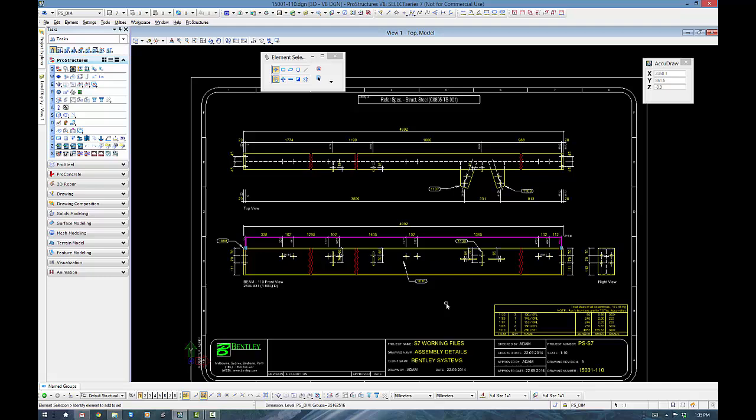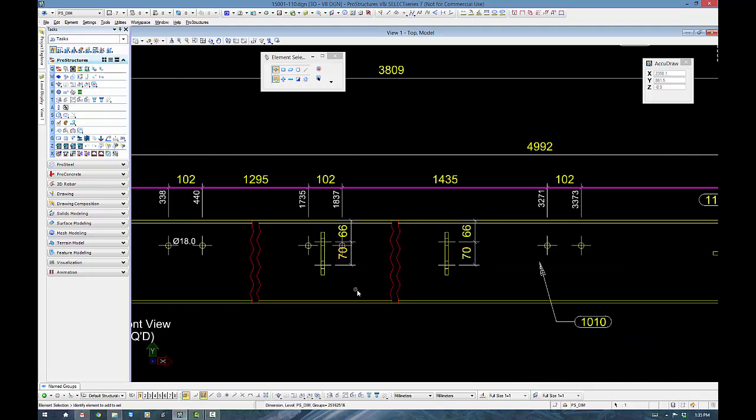Now, as far as other editing goes and bits and pieces, if you've got to physically move a dimension in the MicroStation version, the dimension as a whole is going to try and grab. So if I want to extend those extension lines, I'll need to come to 7, which is modify, and then modify the object. Okay, and it'll just let you drag it out then. Actually works a little bit better than the AutoCAD version.